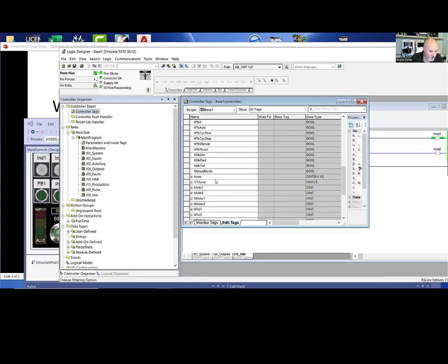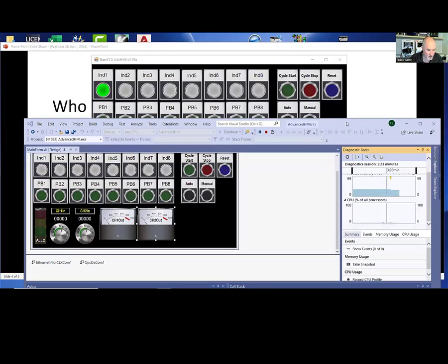and this is what I did on my other PLC, I made a single tag, and I just called it HPB, and then I used a dot, and I used .0, .1, etc. That makes it easier for the student because all they need to do is create one tag for inputs, one tag for outputs as far as digital. So that's another difference on my other HMI. But you can assign these addresses to pretty much anything you want to.